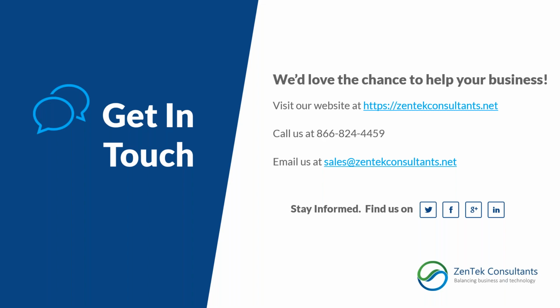Okay, there we go. Question is the survey database. Once I move to 2020 database, is there any way of going back to the previous version? No, there absolutely is not. You cannot revert. And that's why I pointed it out, Derek. I understand your concern. That's very dangerous. And that's why I want to make sure everybody's aware of that. It's a one-way trip. Once you make that change to the database, you cannot convert from the SQLite back to the CE. All right. So be very careful. Make that decision carefully before you do that.